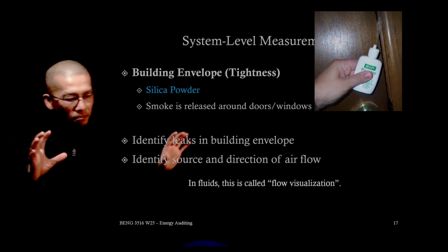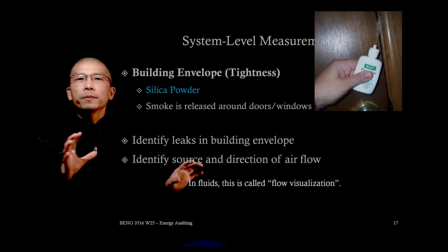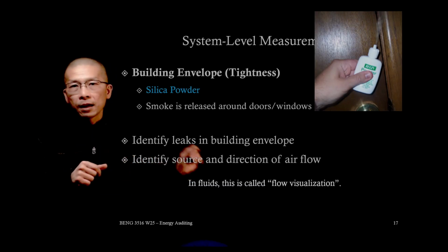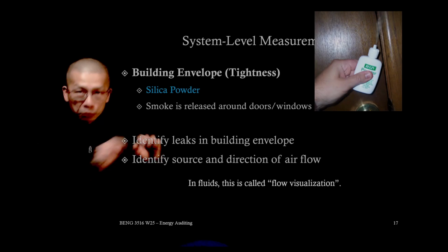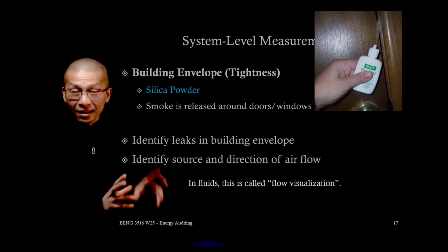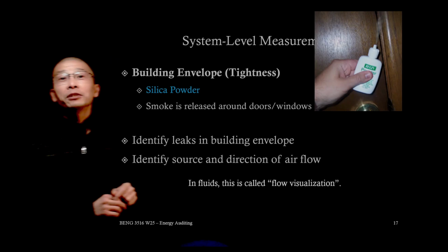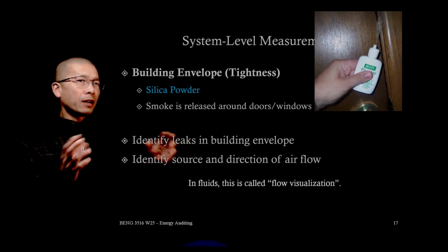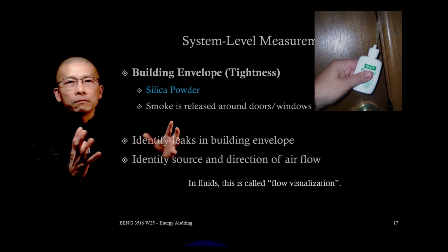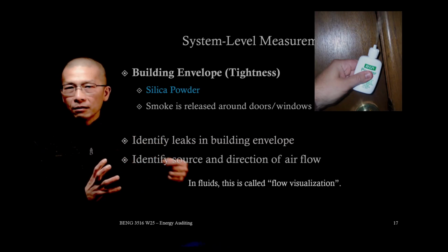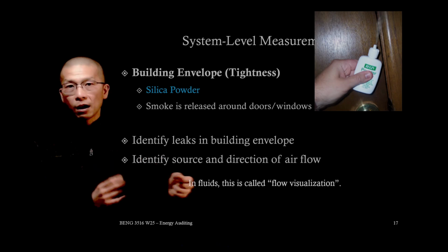So I still remember when the house auditor came to our house and did this door test, and I was asking, how do you read that, right? And guess what? If the house is tightly sealed, the delta P will be larger.